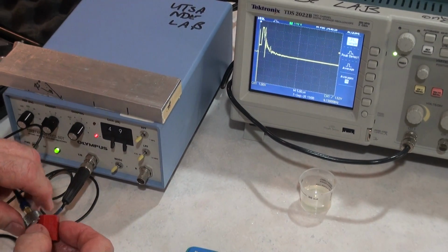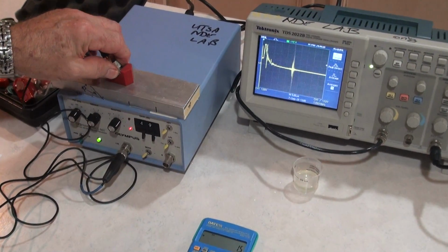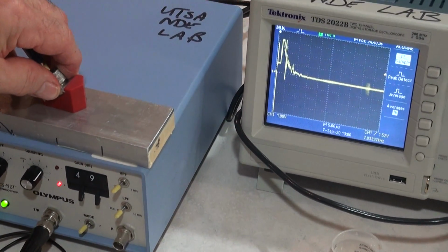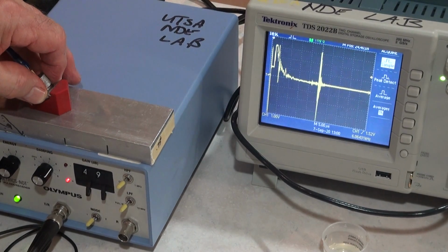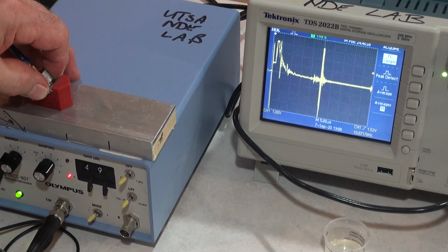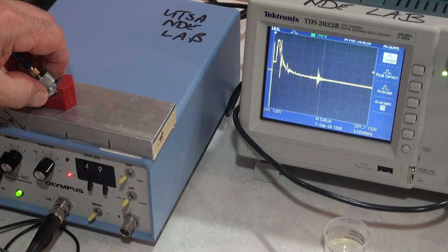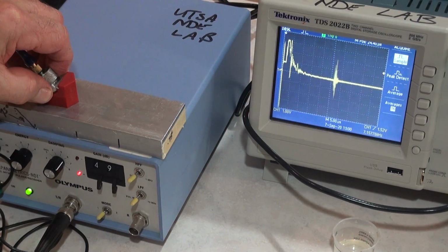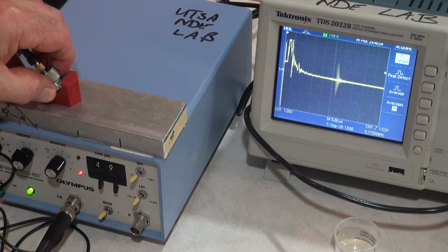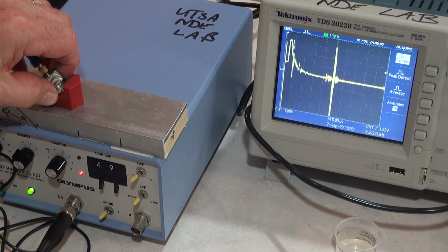So just to show you what this looks like, here's my 45-degree beam, and it's going into the aluminum block, and it sees a big signal right there. You see the signal about 25 microseconds out. And what's interesting is, one of the things you can also see is that it becomes bigger and then smaller and bigger and smaller, and where it peaks is where the signal actually is. So that's the peak right there.